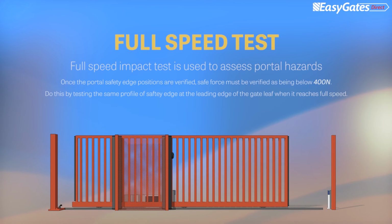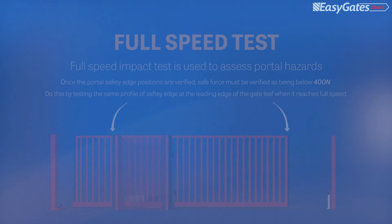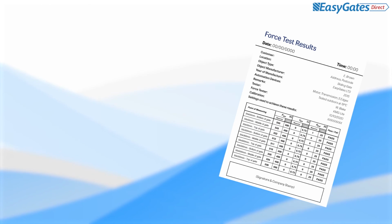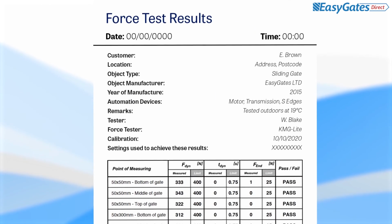The sliding gate full speed impact test assesses the suitability of portal fixed edges. These edges should be of the same type used on the leading closing edge, to ensure safe values are met. Following completion of these tests on any type of gate, remember to create reports or documents presenting the values recorded.